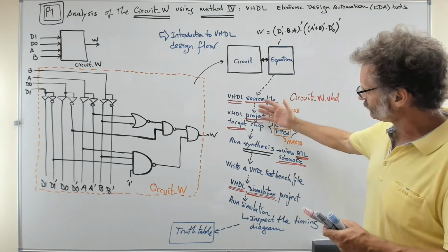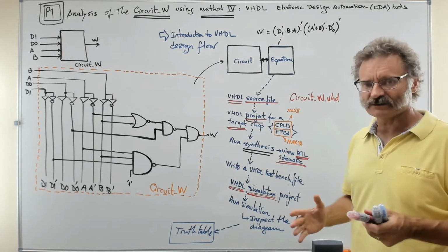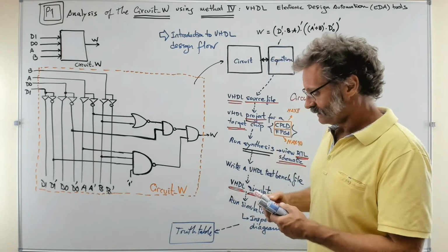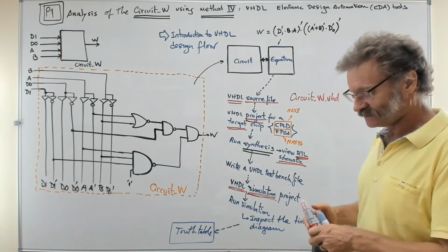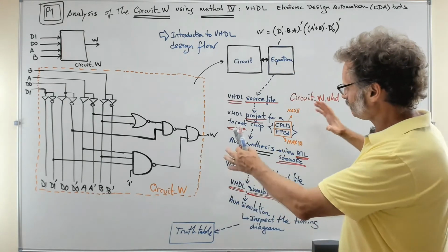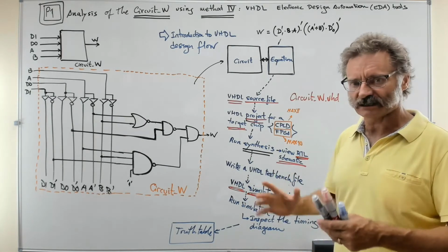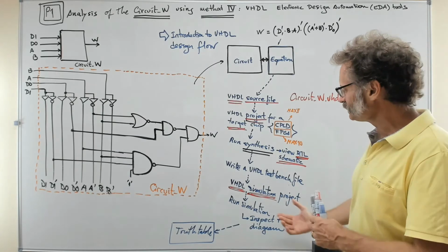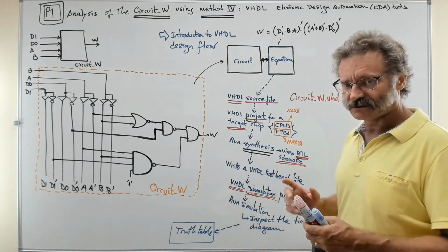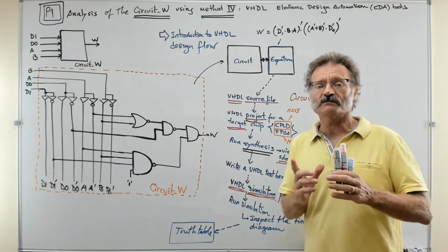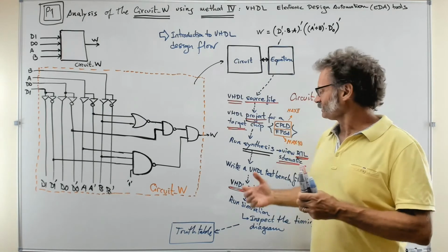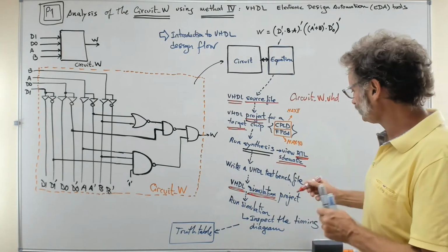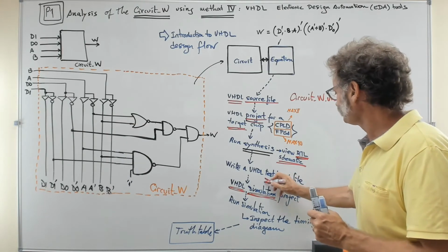Basically, after synthesis, we have to have another project here, which is going to be a simulation project. And to do so, we will keep the VHDL environment all the time. So we're not going to go anywhere else but use VHDL all the time. And to do that simulation, what is required is what is called a VHDL testbench. That is the word, testbench.